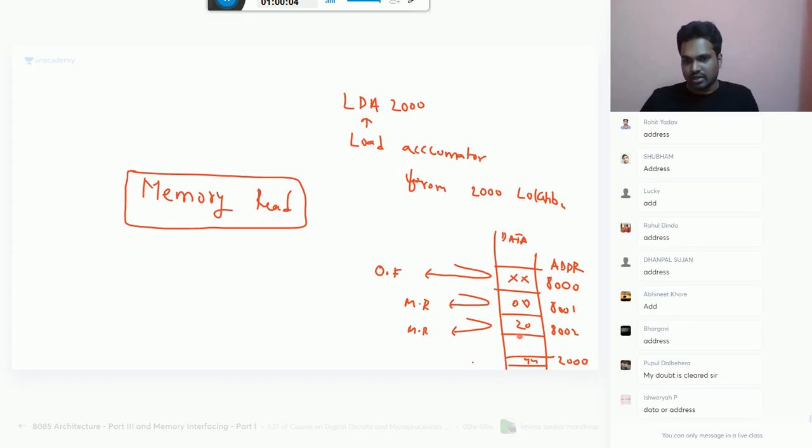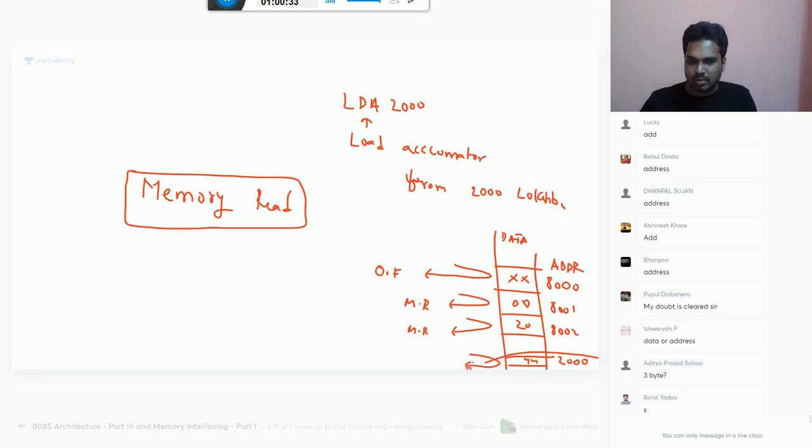Okay, so this address is stored in two parts here. A 16-bit address cannot be stored in one location. Maybe that is your doubt. So the computer will read this 00 like data. The computer doesn't know anything. Once it reads, because of this instruction, it will go there, the pointer concept, and read. It is 3 bytes only. This is not part of the instruction. It is not 4 bytes. It is outside. Then it will go there and do another memory read also.